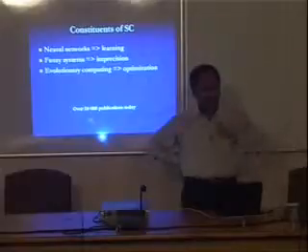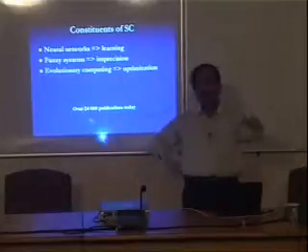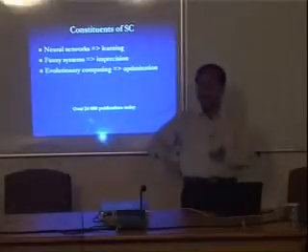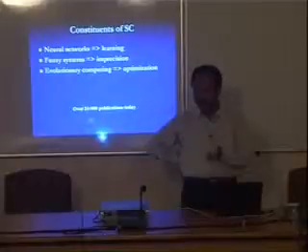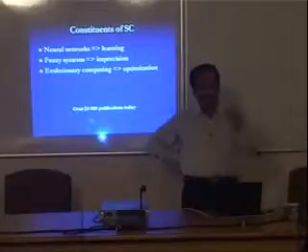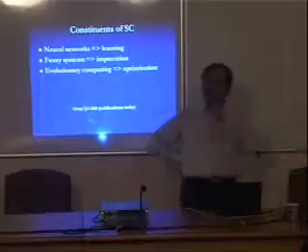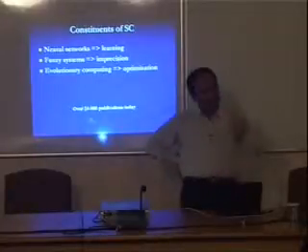Everybody must be knowing about this. For a DC motor, we represent x dot equals Ax, or any system you take, it is a differential equation. Right? Now, once you get this A matrix, that is called the state matrix, you will design your controller based on that A matrix.